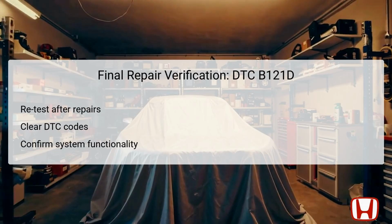Upon completing the necessary repairs, it's crucial to verify the effectiveness of your solutions. Start by retesting the vehicle to confirm that the new or repaired components operate as expected. Clear any stored DTC codes from the climate control's memory, and then restart the vehicle to observe if the DTC appears again during normal operation.